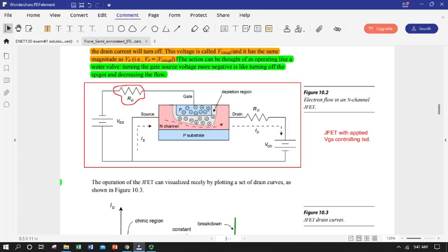So we're going to create an effective negative charge in the p material, especially up near the p-n junction, and that's with these negative signs with the circles. Remember, a circle means an effective charge because we've withdrawn what would otherwise have been there. So we withdraw our natural p dopant holes from the interface. We create a net negative charge at the interface.